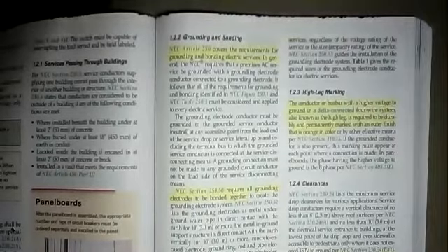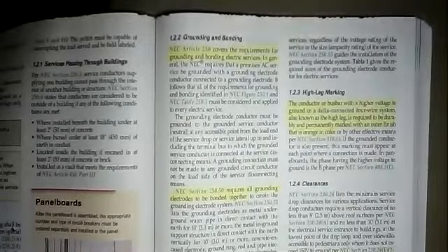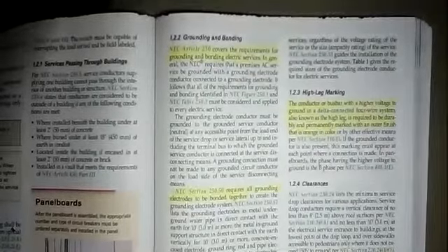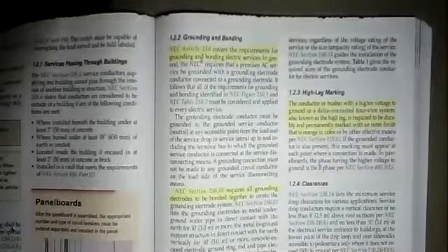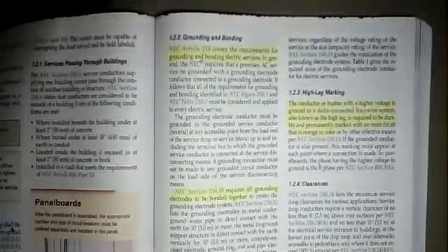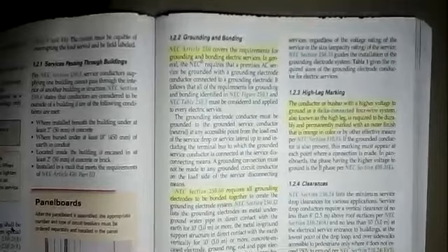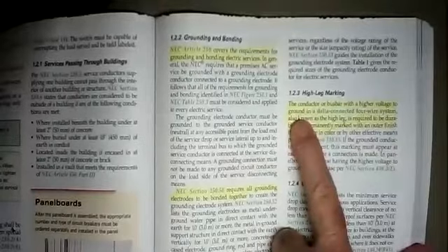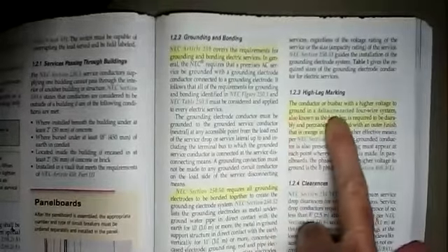They might put it around the entire building, or they might do corner deltas. Whatever grounding electrodes are present on a job have to be bonded together. All of the grounding electrodes on the entire establishment have to be tied together.